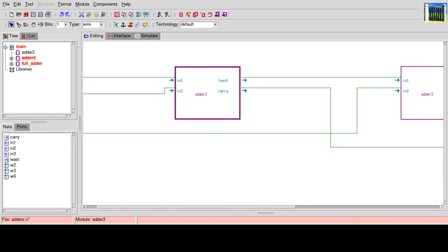In other words, inside of that box is the exclusive OR and the AND gate. Now I'm going to feed the 2-bit adder 2 inputs, and I'm going to get 2 outputs. I'm going to get the least significant figure out, and you can see the highlighted wire on top, and then you're going to get a carry out. So again, you feed 2 numbers in, and you get a least significant figure out and a carry out.